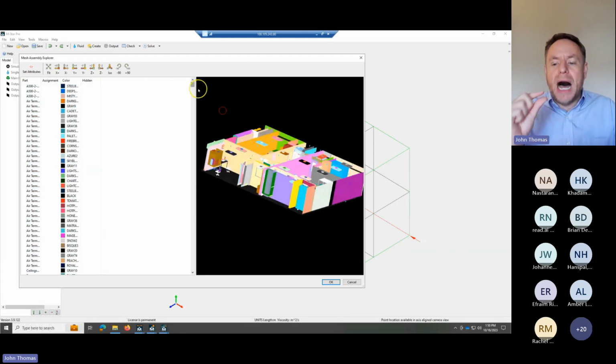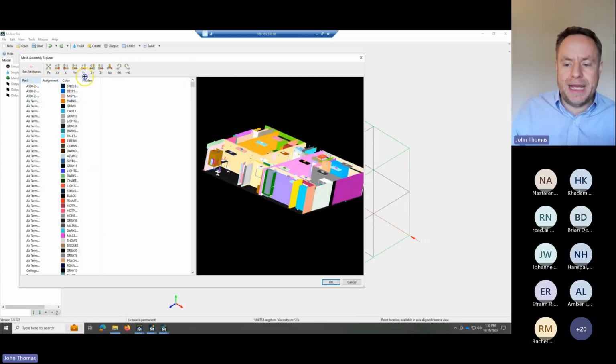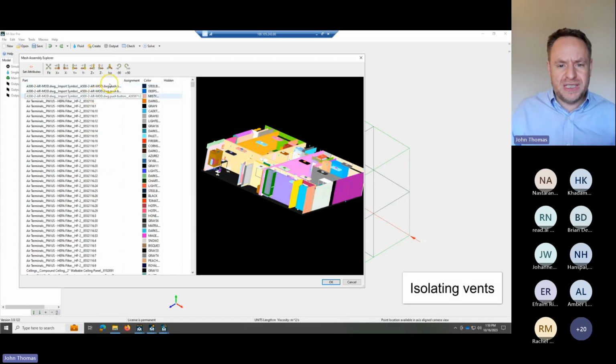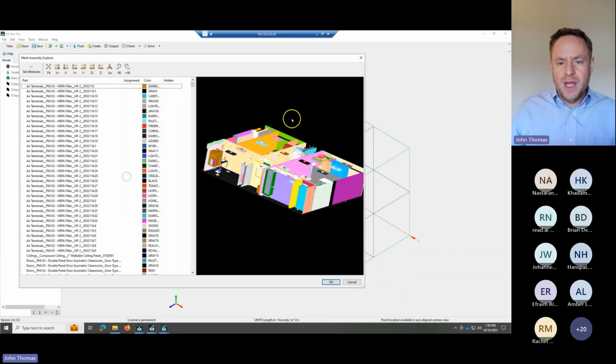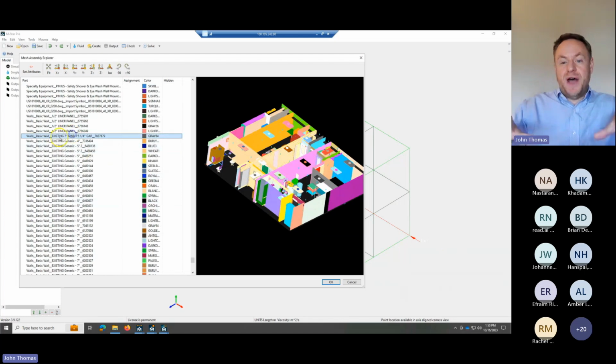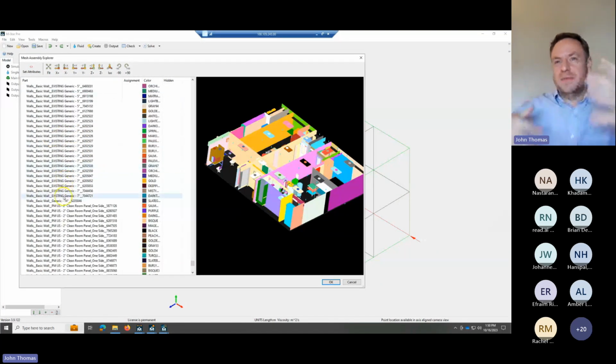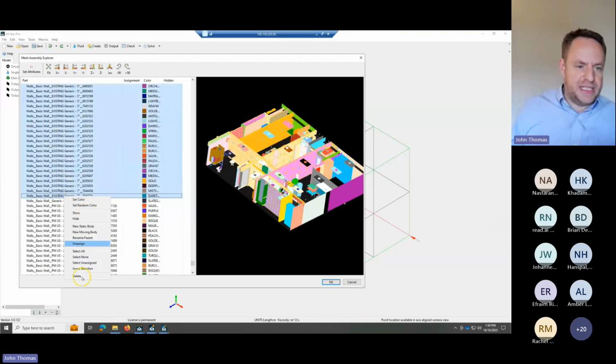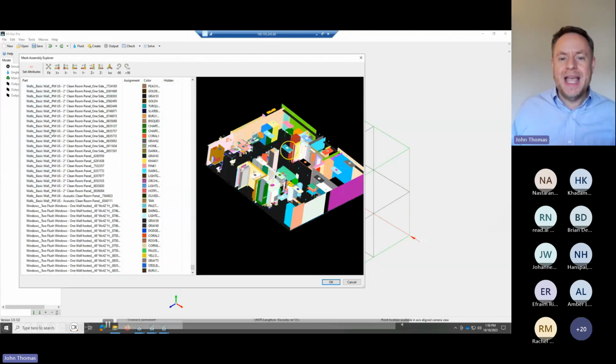So I'll do a modicum of cleanup here. I'll delete a few of these where the walls are removed. It's a modicum of cleanup to take this BIM file from having some as-built features, converting these existing walls and just blasting them away, and getting this down to the as-designed features.